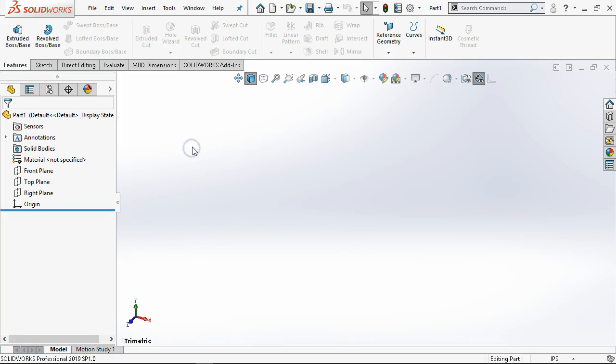So my S menu popped up. What I was mentioning about the mouse gestures: if I hold down the right mouse button and drag to the right, the donut will pop up, and then you can pick any one of those, and when you let go, in that case it'll take you to that view. I really didn't want to go to the right view, but I'm in the right view.